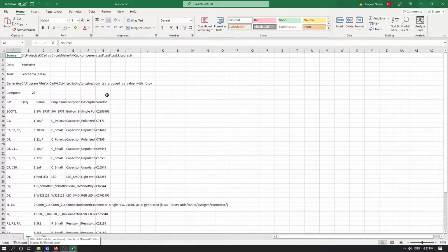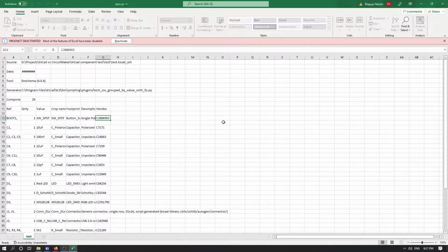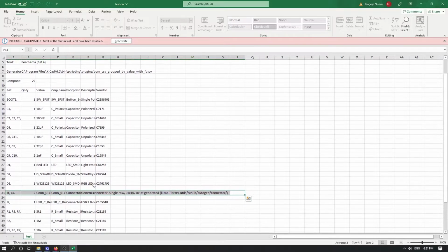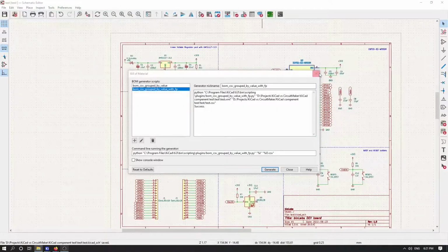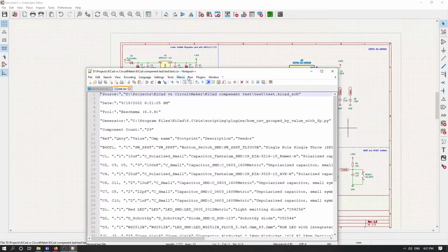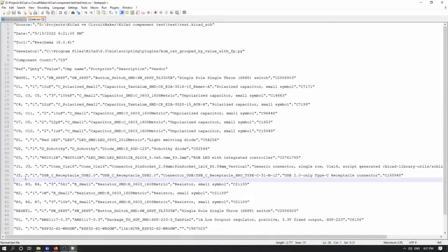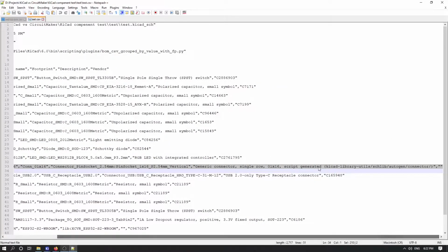And now we can double check. So yes, and basically here we have now our vendor field, and every component should have one corresponding to this, except of course J1 and J3, which are through-hole pin headers that cannot be done via JLCPCB. So either we can remove this line or just leave it as is, but we have everything else installed. So of course, let's double check here like this. Exactly. So yeah, we have these single row pin headers, but for that we don't need any part.